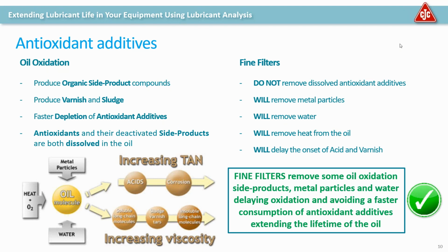And there's equipment that we can use to remove those contaminants from the oil. Same with water. Water can be tricky, but there's different forms of water. There's free water, there's dissolved water, there's emulsified water, and there's different techniques such as air stripping or a coalescer, or even just simply absorbing the water if it's at a lower level that can help to address that issue.